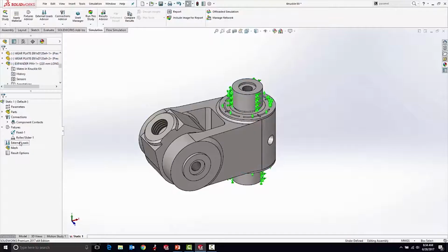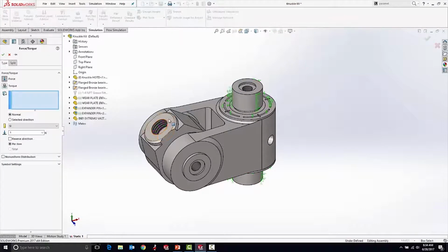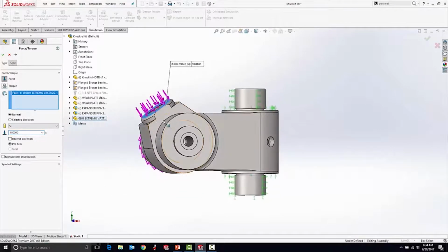Awesome. So next I need to define my loads. This is another kind of boundary condition. I'm going to simply put a force of 180,000 newtons on the pin where my cylinder is going to be attached. That is the capacity of the hydraulic cylinder that's going to be lifting and lowering the boom arm. So this is all very simple and intuitive so far, right?